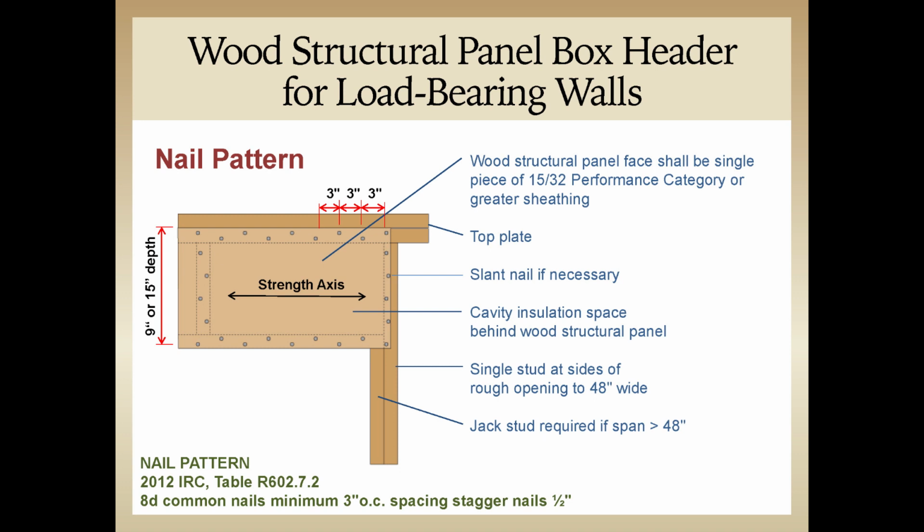We do want to note a few requirements for this. First, 15/32 category panels must be used. So commonly, 7/16 category panels are used for wall sheathing. And if that's the case, the 15/32 panels could be used only where box headers are designed. And the minimal thickness difference shouldn't cause appearance issues with the water-resistant barrier and siding over top of the sheathing.